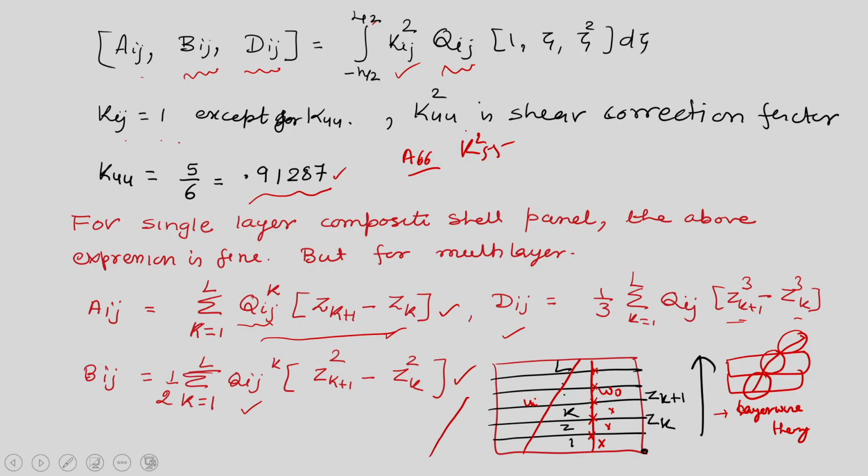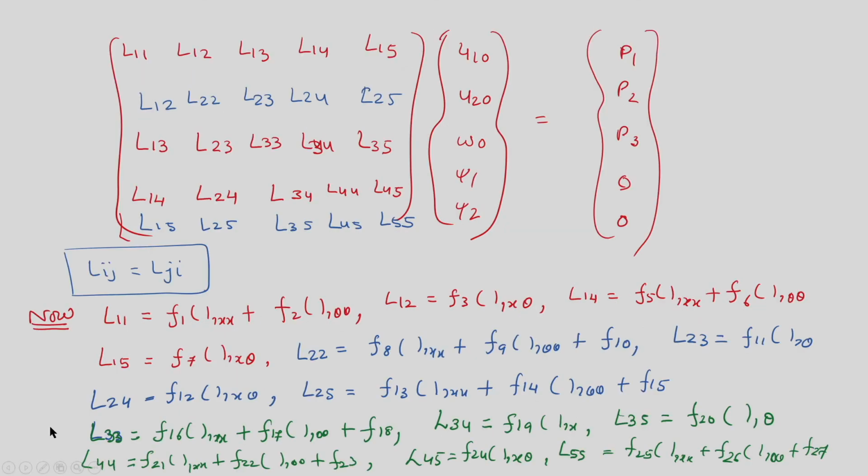But in general, if you are interested in the deflection behavior or in-plane bending stresses, they are pretty good, but the transverse shear stresses are slightly away from the 3-dimensional solutions.